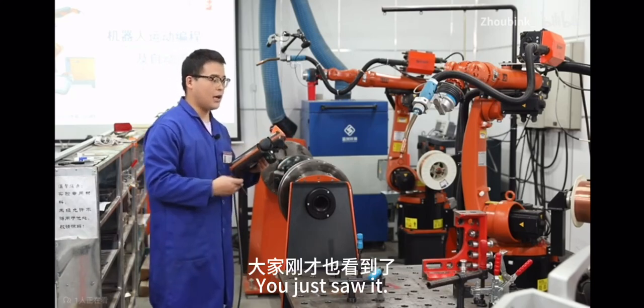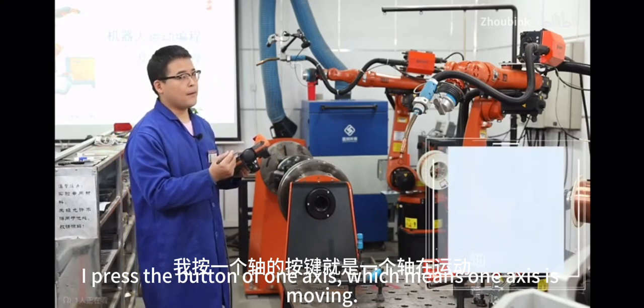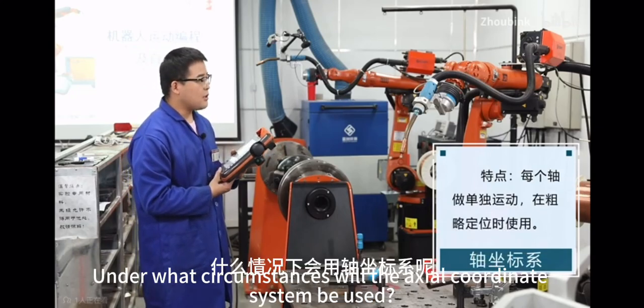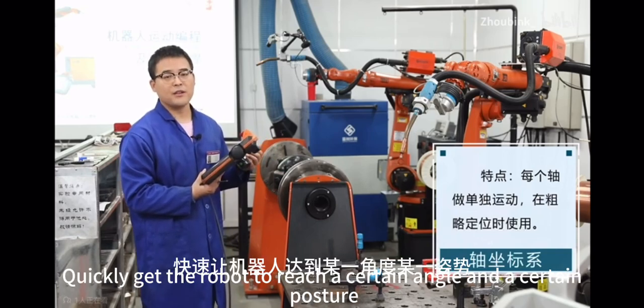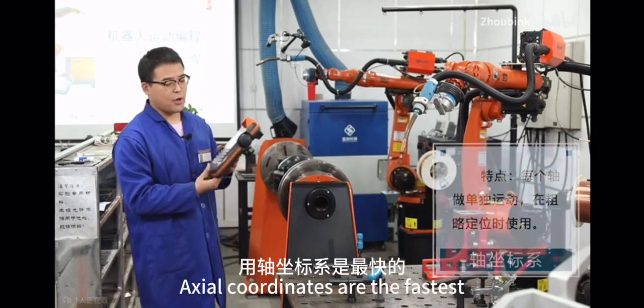You just saw it. I press the button of one axis, which means one axis is moving. The characteristic is that each axis does a separate motion. Under what circumstances will the axial coordinate system be used? Use the axial coordinate system to quickly get the robot to reach a certain angle or certain axial coordinates. It is the fastest.